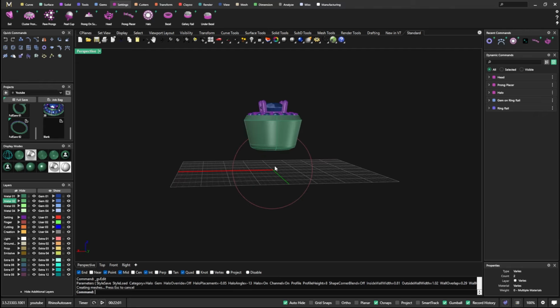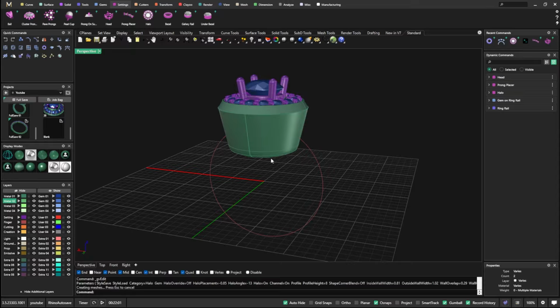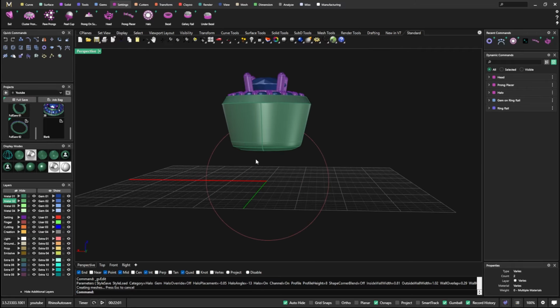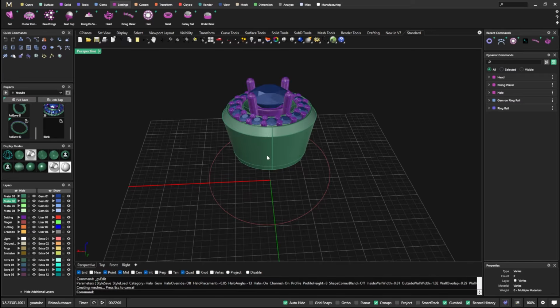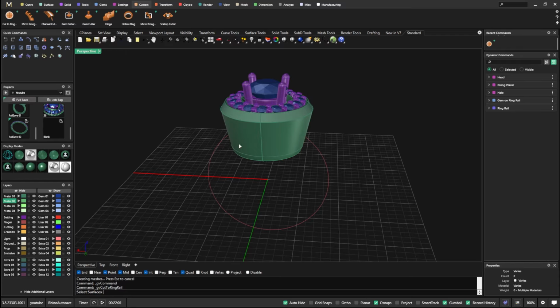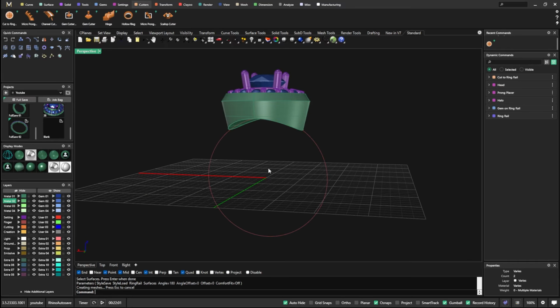Now we want to continue to put a shank on it and get some kind of design going as well. That's pretty thick, maybe we want to thin it out some. So there's lots of things here we can do. First thing would be to just go to your cutters, and all this is still parametric. So you can select that and hit enter, and it's going to automatically cut.